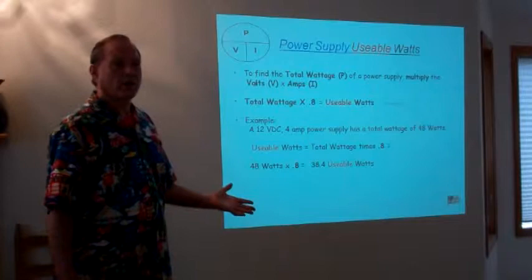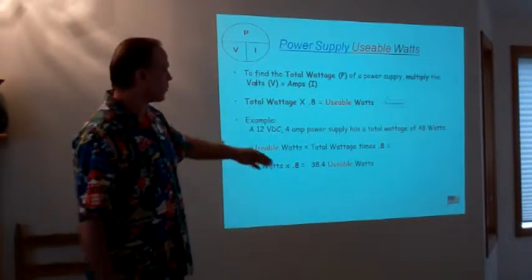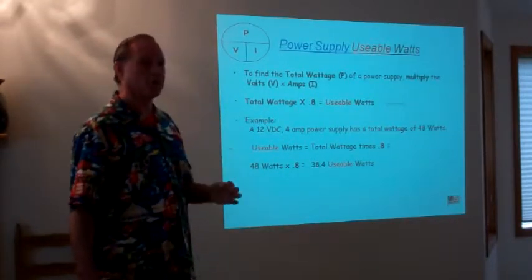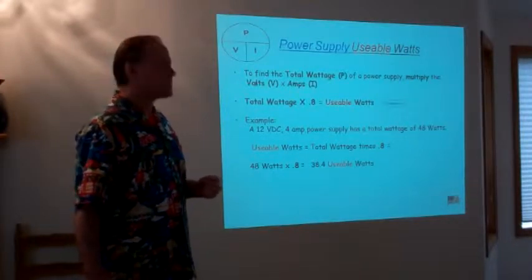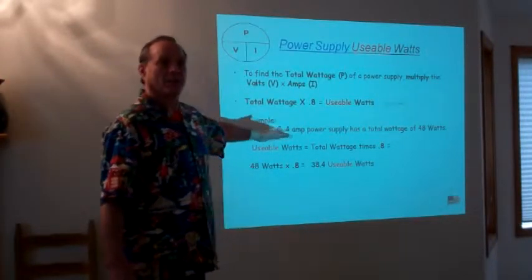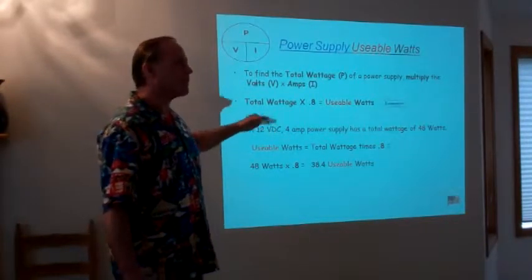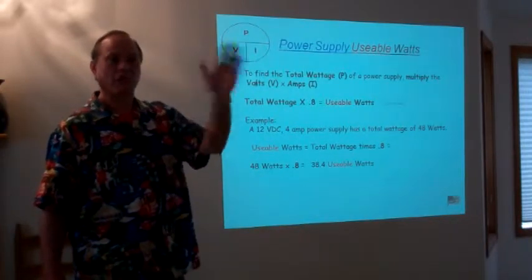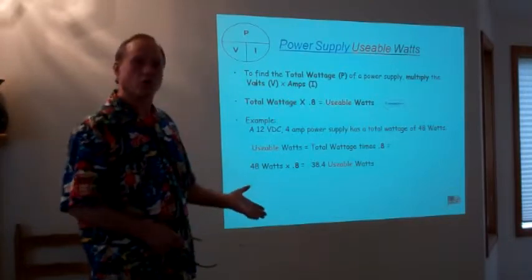Now that's not to say that those other watts aren't still there. They are. And yes, you could run your system up higher on that. You could run it to the full load, to the full wattage of that power supply. But what you're going to do is decrease the life expectancy of that power supply. This also, as we're going to see in a little bit, will allow us to take into consideration ambient conditions and other things that will affect our circuit, such as cable runs that are sitting out to our loads from our controllers, for instance.